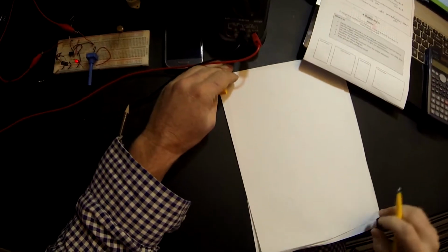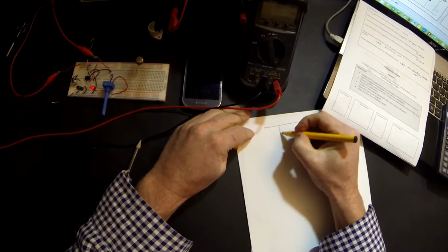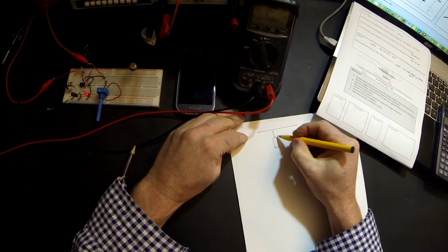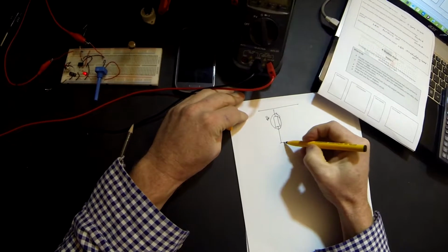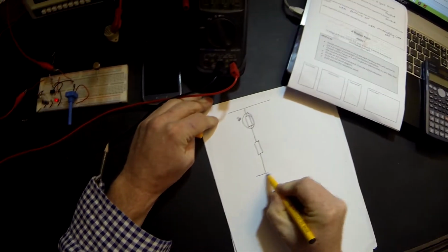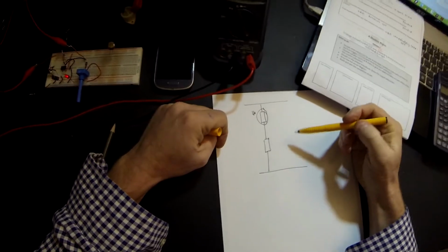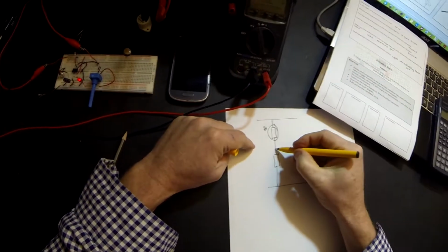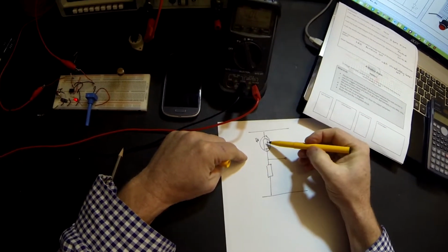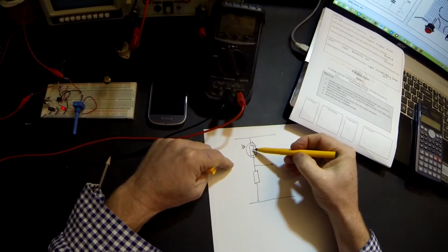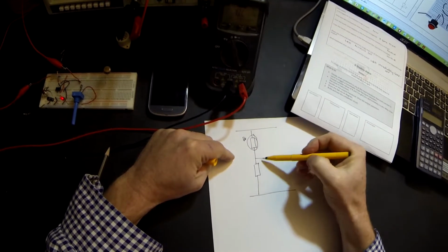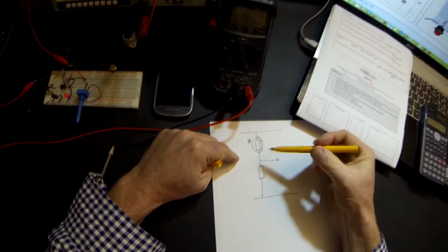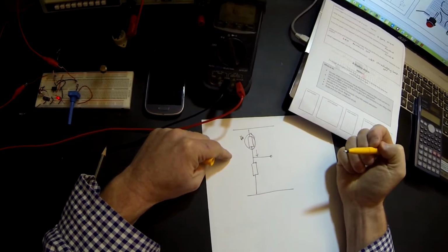Now we know from previous experience that an LDR with a pull down resistor will do fairly much what we need, because the output of that circuit, when light stops falling on the LDR and it gets darker, we have a higher resistance across it, therefore a greater voltage drop, therefore the voltage should go down when it gets darker.